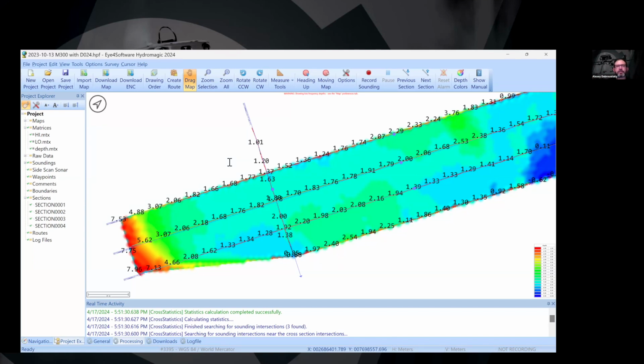This is why you need to fly in RTK mode or with a PPK receiver, because for every moment of time you will have the elevation of the drone in space, and you can calculate very precisely the elevation of the bottom.